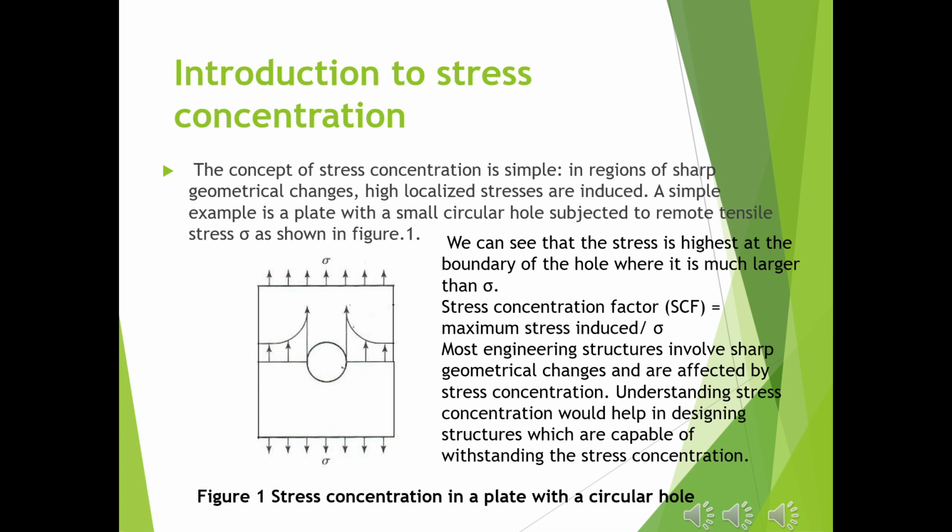This phenomenon is called stress concentration, where the stress is not uniformly distributed over the area. Instead, close to local stress raisers like holes, notches, fillets, bosses, etc., the stress becomes much higher than the nominal stress. This phenomenon is called stress concentration.